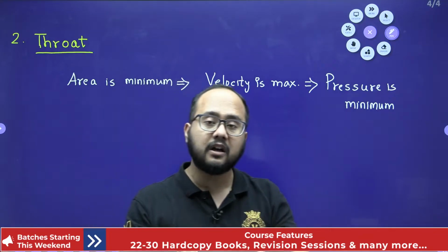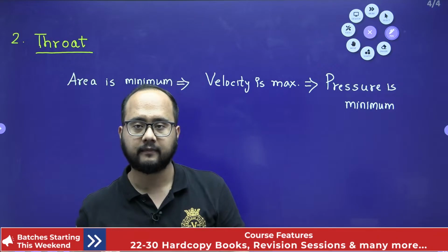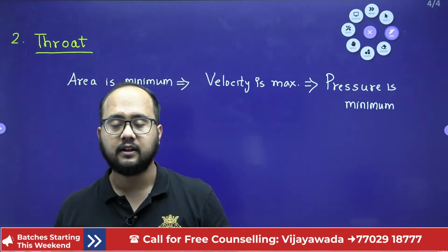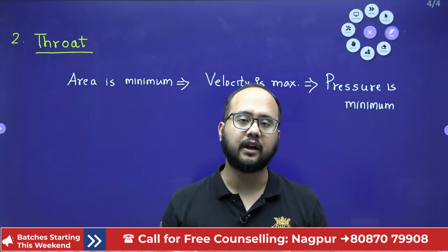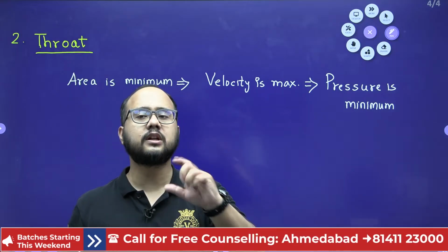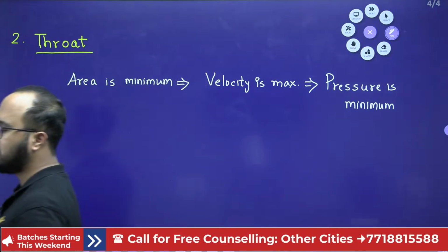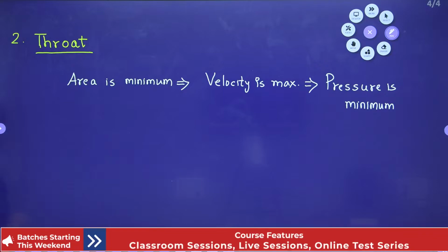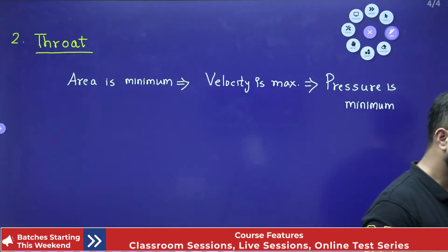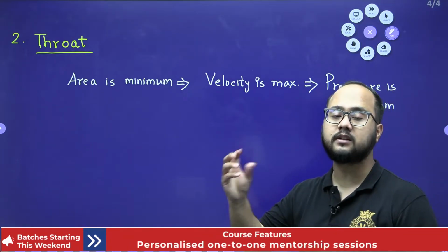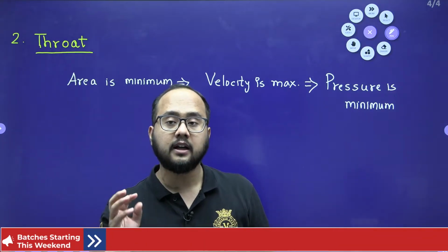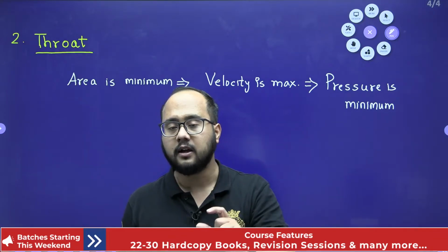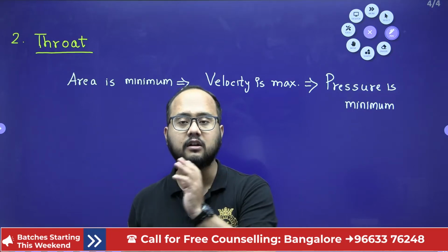Now, very important point. Whenever during the flow the pressure reduces, what actually happens? Please try to remember the point. During the fluid flow, whenever pressure decreases, what are the possible chances? If the pressure decreases, what is going to happen at the throat portion in this case? Tell me, everyone. See, whenever pressure decreases, it should not decrease beyond a certain point, because then the chances of cavitation will be there. So we cannot decrease the diameter of a throat beyond a certain limit.